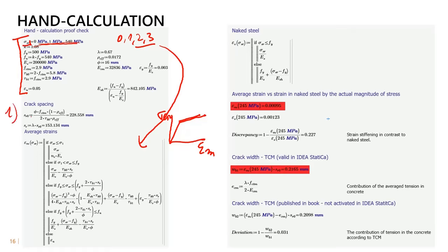So at first, I need to calculate the crack spacing. As you can see, the value is 229, and 229 was also the value displayed after the solution in the CSFM. So this is the fundamental crack spacing, s with the subscript r0. If you have just s with the subscript r, this is the averaged crack spacing, because here is the lambda, and this value is coming to all the equations that are here. So this is the reason why we are considering average strain.